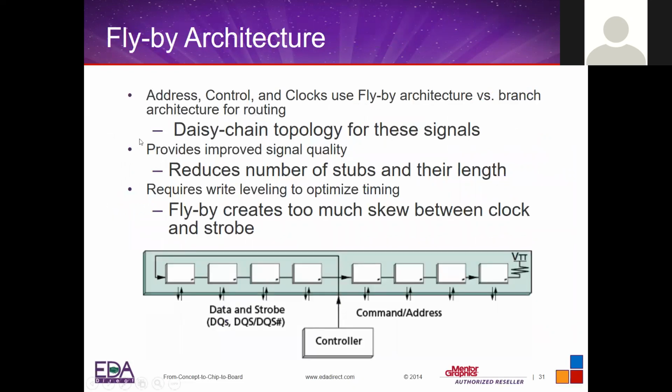And then with DDR, there are things like flyby architecture, where you have signals that are daisy chained, for example, address lines, and you have signals that are point to point, right? Source synchronous. For example, data, DQS, and the data bit. Controller is driving the address based on the clock, but these address lines are connected in series. So if you have, for example, 8 chips, and if the controller is driving one address line, it has to drive this in a serial fashion.